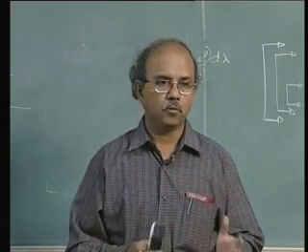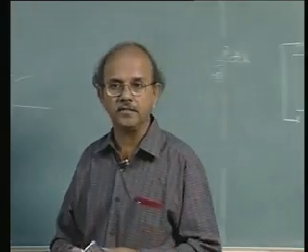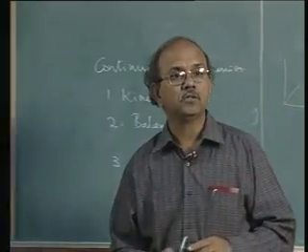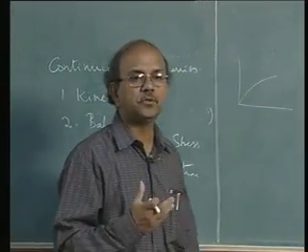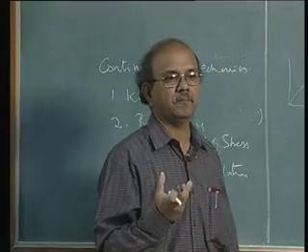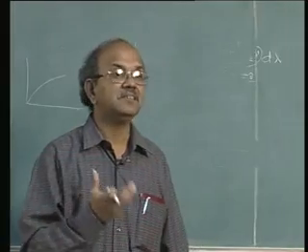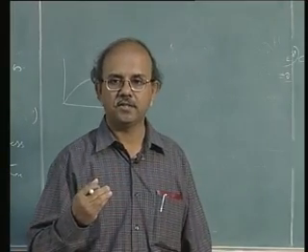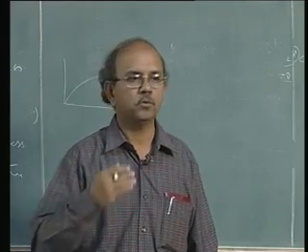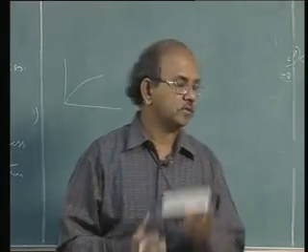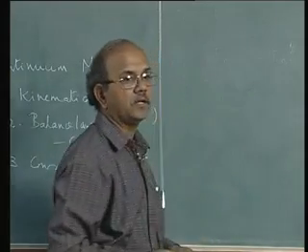And the other packages, which are good packages, not only ask you to define this stress-strain relationship, but also ask you to take a material model. They would say, if you're going to define an Ogden model, define it and then give me the stress-strain relationship. So this shows that there is a lot more theory in the development of constitutive equations. That will take us some time to get to.